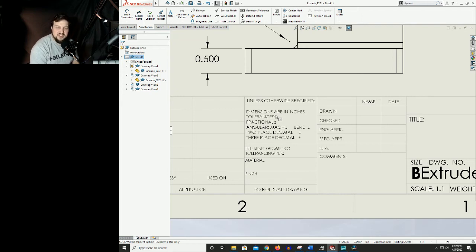A tolerance is the amount of give on either side of that we're allowed to properly make the part. As engineers and designers, we have to look at a component, the place that it's used, the assembly, how everything works together, to decide what the proper size could be. So say we want 3 inches. 3 inches will fit inside the spot that we're trying to make it fit. If you go anything over 3 inches, it absolutely will not fit and cannot happen.